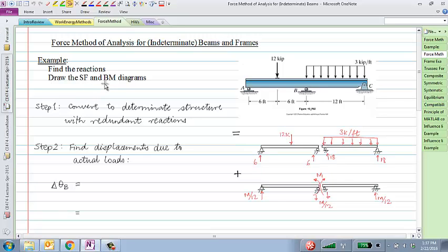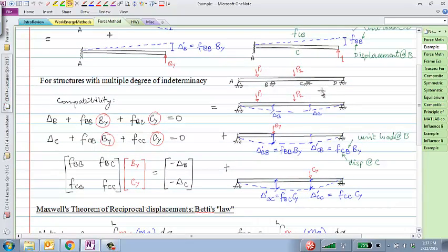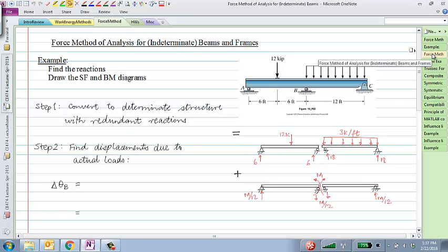Okay, so going by what we had just discussed on the previous page, if you have an indeterminate structure, you remove a couple of the supports and you apply a redundant force there and solve and so on. You can do that, but there might be a better way to solve this particular problem. The key thing here is to choose an underlying determinate system in such a way that it simplifies your computations. So as this figure shows, one might be tempted to remove this support B and just solve it as usual, which is great and fine. You will still get the same answer, but it would end up being a longer method, right?